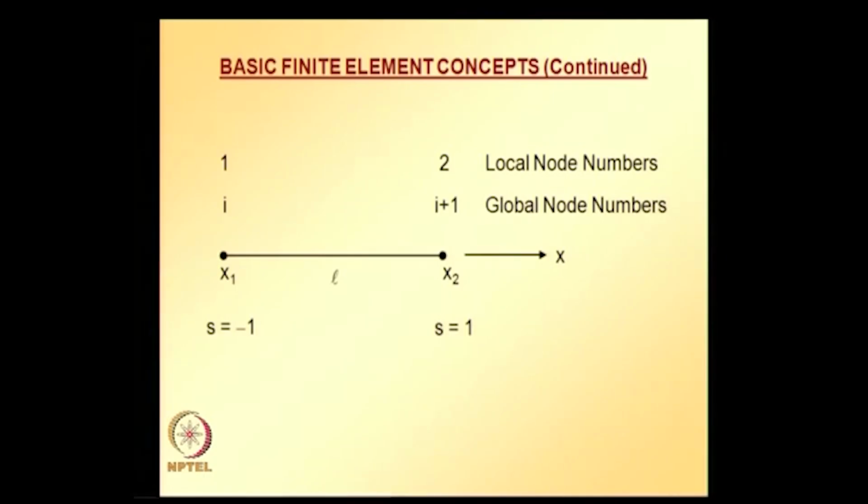and here I am going to introduce you to a new concept. Later, when we are actually assembling the stiffness matrix or the force vector, we will be using numerical integration scheme. At this stage, we will be using Gaussian quadrature, and the integration becomes simpler if your element ranges from -1 to 1.